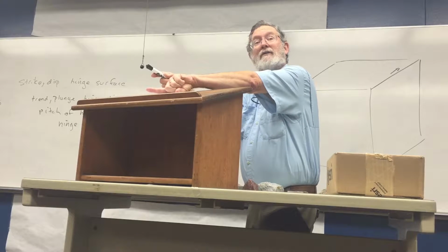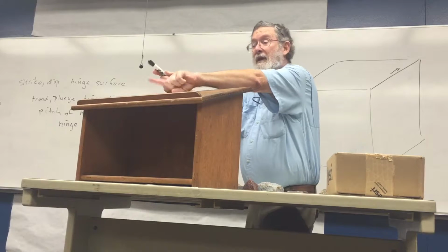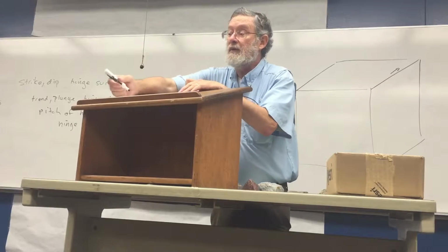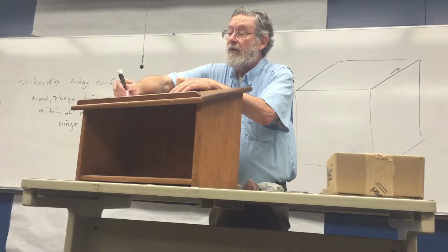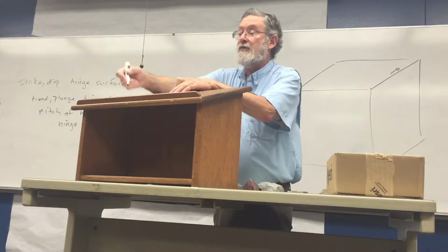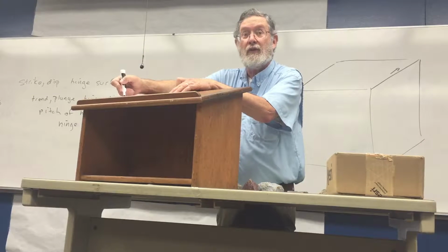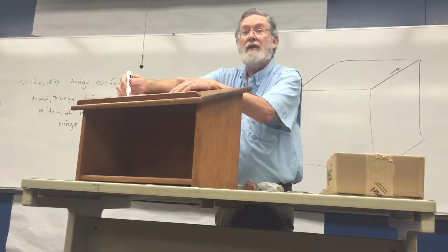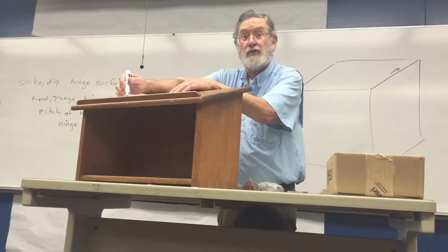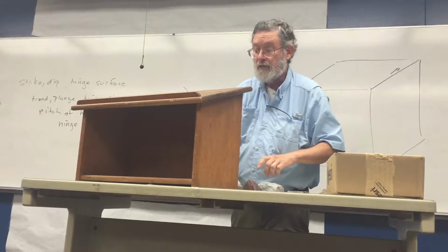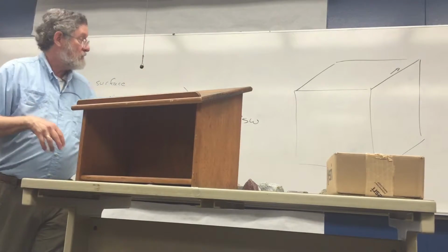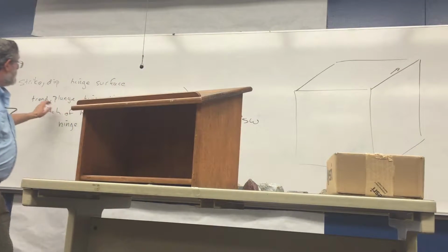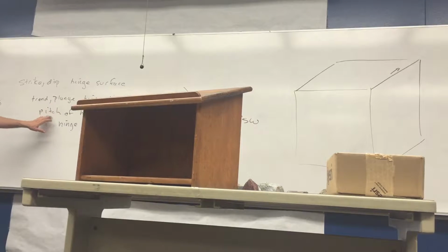Then we talk about the pitch of that, and the pitch is simply the angle within the plane itself, measured from the strike line, measured from the horizontal line to the plunging line. That's the pitch. Okay? So we use those different descriptions of orientation to talk about strike and dip, trend and plunge, and then pitch.